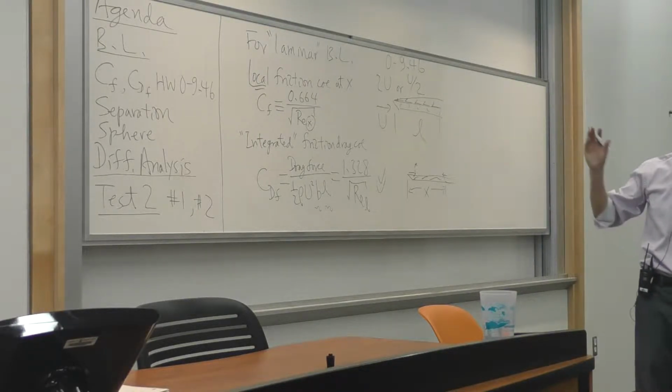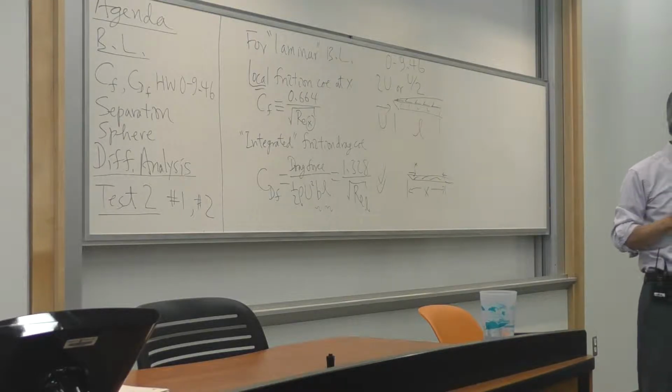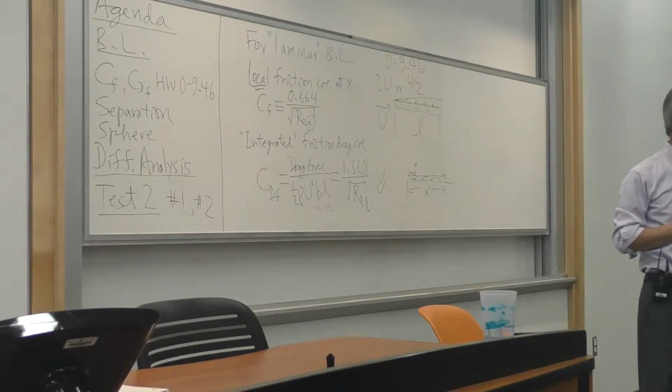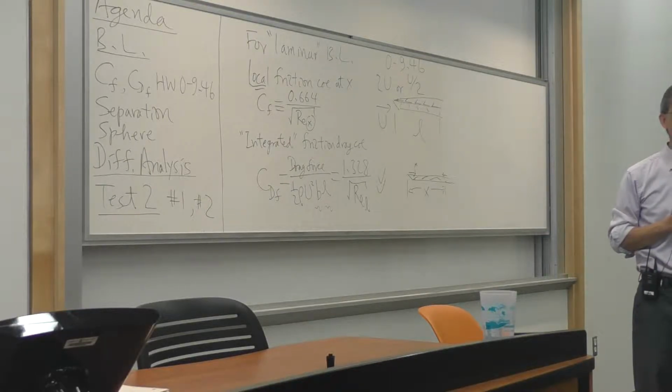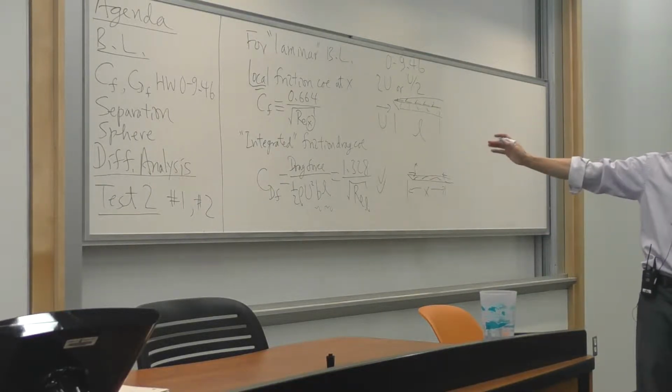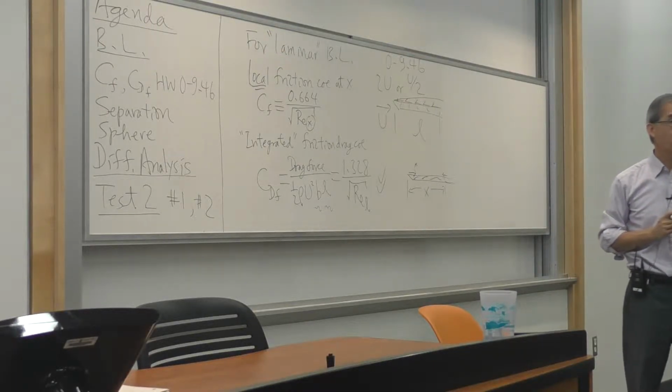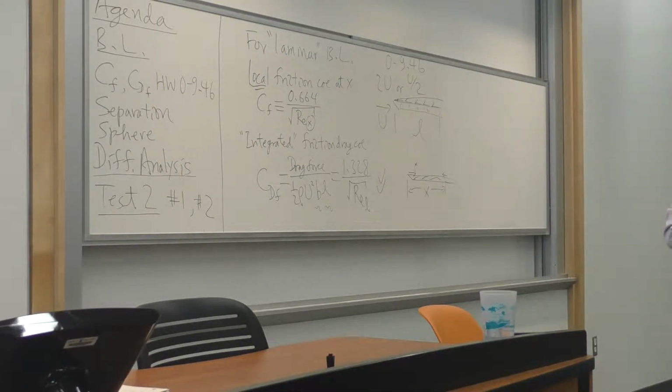It is true for laminar and incompressible flow. So very restrictive, but it gives you a little bit of taste of how one can deal with friction due to shear, due to viscosity, purely, but no contribution, at least for a simple plate, of pressure drag, or so-called form drag. Is that clear?